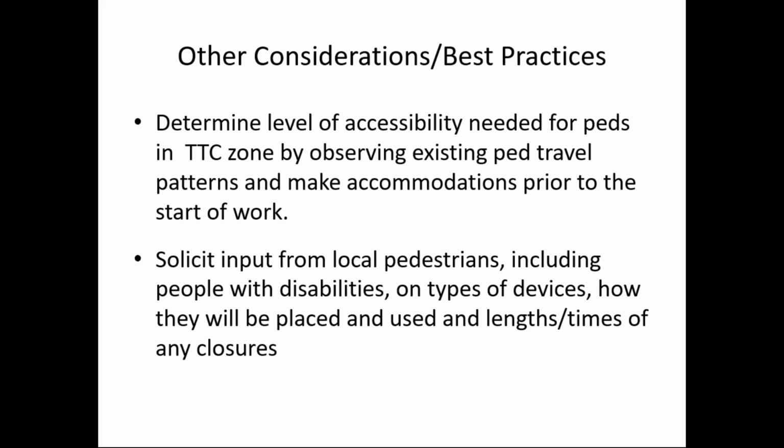Especially on longer term projects, larger scale projects, I would like to suggest observing pedestrian travel and their patterns so that we can make accommodations for that in the design of the temporary traffic control. Same way, get input from local pedestrians, including people with disabilities, on how the devices are going to be placed and the lengths of time of closures and that sort of thing. They may be able to provide helpful information.